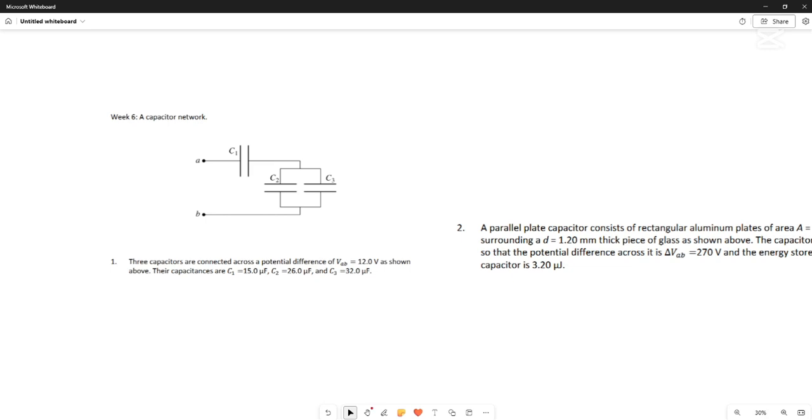The important thing here is that the only downside to using a Thevenin equivalence is that when you take a more complex circuit and turn it into something simplified, you do lose information. So you have to be careful that you don't simplify the circuit too much and lose the information that you may want about a specific component.